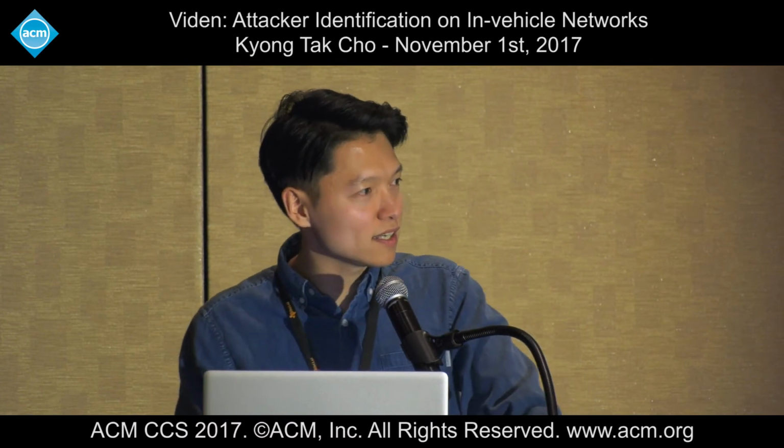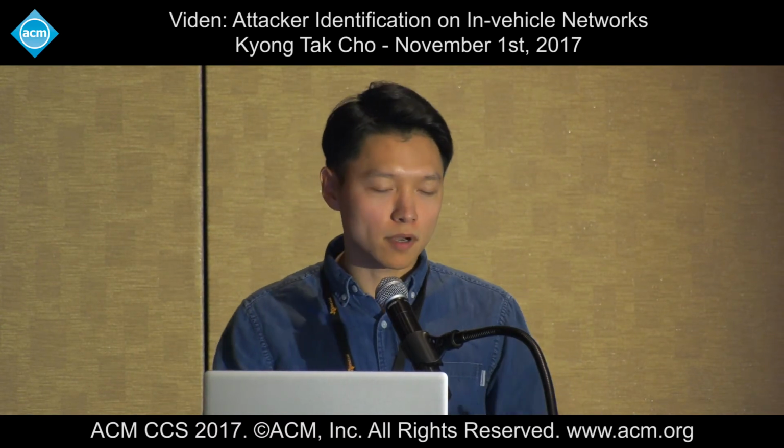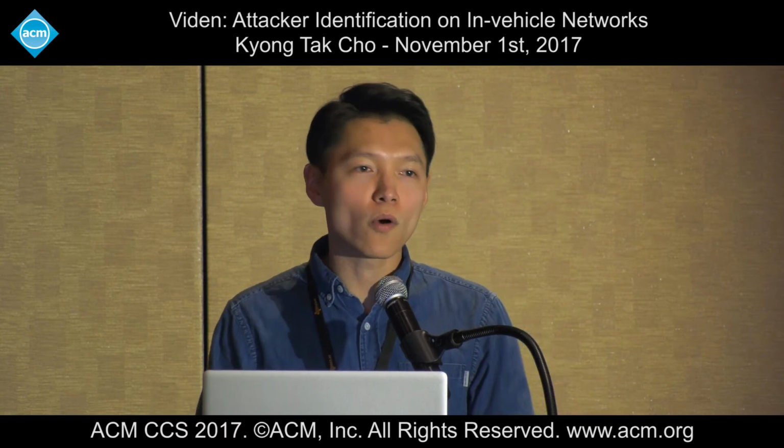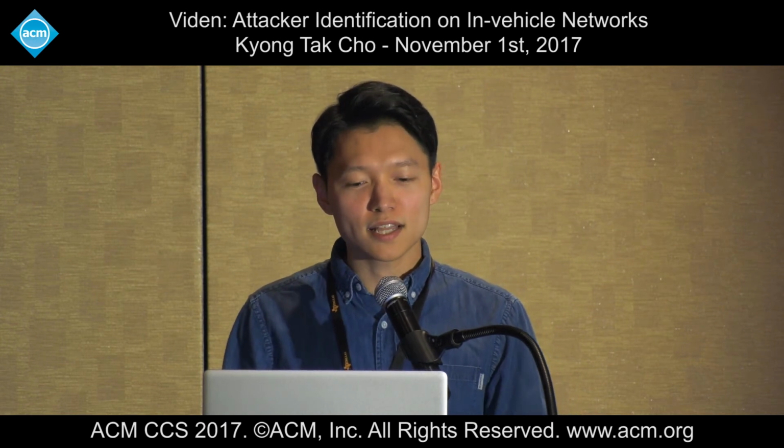Ideally, this would run with the IDS, because I believe automotive OEMs are trying to implement IDSs on the car. With those IDSs, if you have this simple function, you can not only detect the presence of an attack, but as soon as you detect one, you go through your models and pinpoint the attacker. That would tell what ECU to isolate within that network. People are talking about that as well, or how to shut down that specific ECU, and you might want this kind of scheme. It's about narrowing down all the possible candidates for the attackers, and then helping to deal with them through various means.